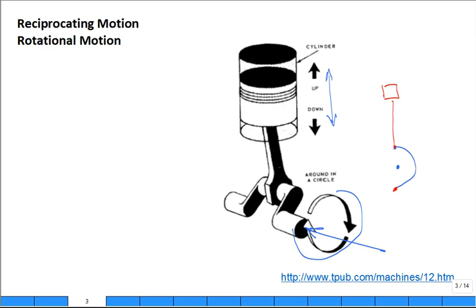It's now at bottom dead center. See that? So maybe I'll draw it again. This length is the same right here, so I'm not going to try and change that length, but I'm going to try and put it over here. And now the piston's here. So the piston went from top dead center to bottom dead center with half a rotation of the crank. If you do another half, the piston goes back from bottom to top.